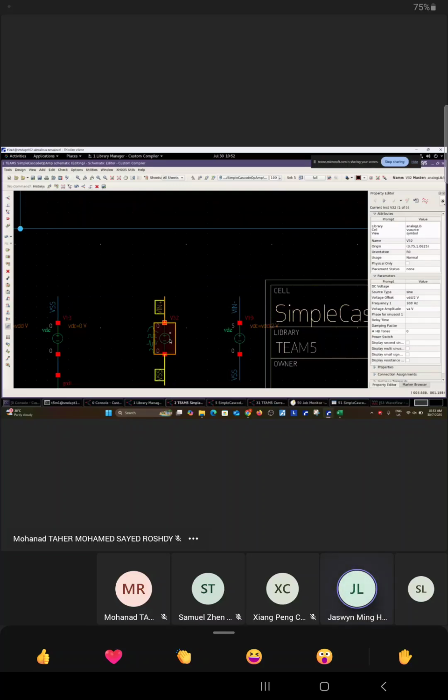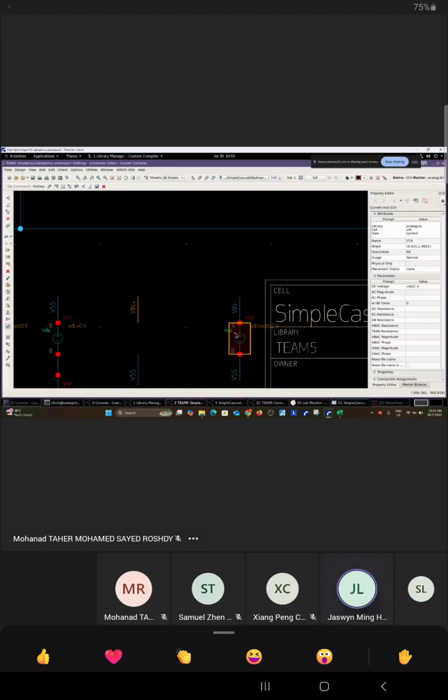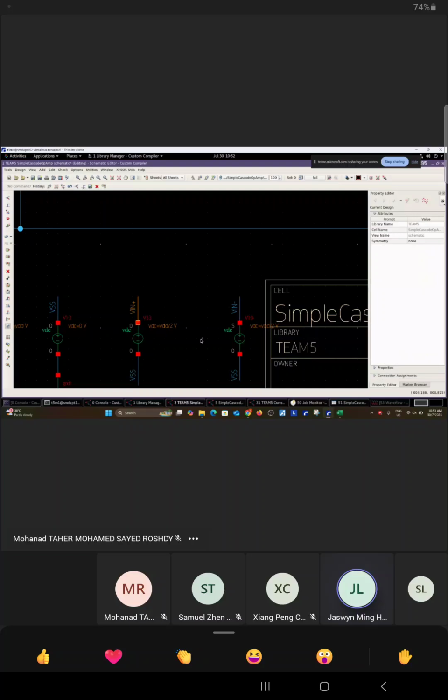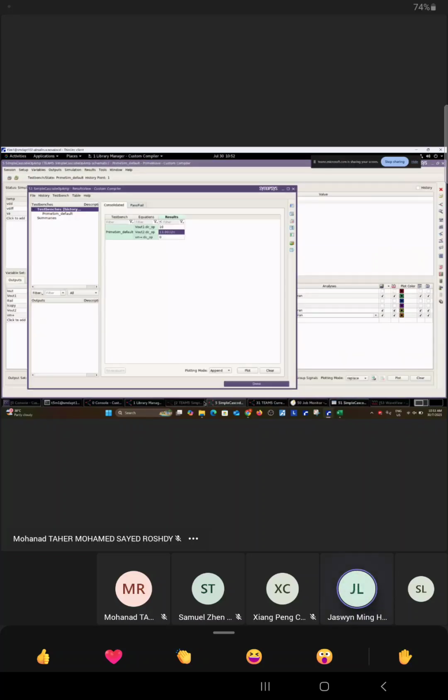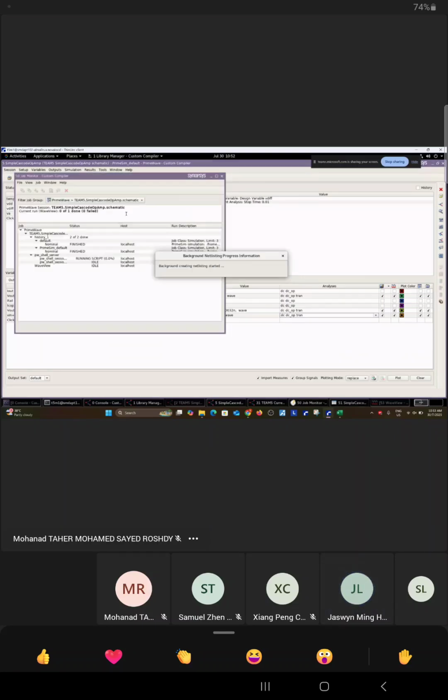because right now we are setting for DC operating point. So this one is in AC, so very hard to tell actually. Yeah, you try to remove this, then we check again. Yeah, put back the DC here. Copy and paste it. Yeah, same thing. Okay, now you run the DC operating point again. Yeah, you run it again.